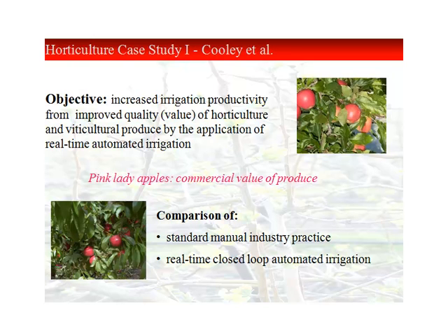What we mean by real-time closed-loop automated irrigation is that the data was collected in real time, that there was a loop of information, that is, history informed the data. And the automated component is that irrigation solenoids were turned on and off based on the algorithms that were obtained from the data collected and the levels that we developed.